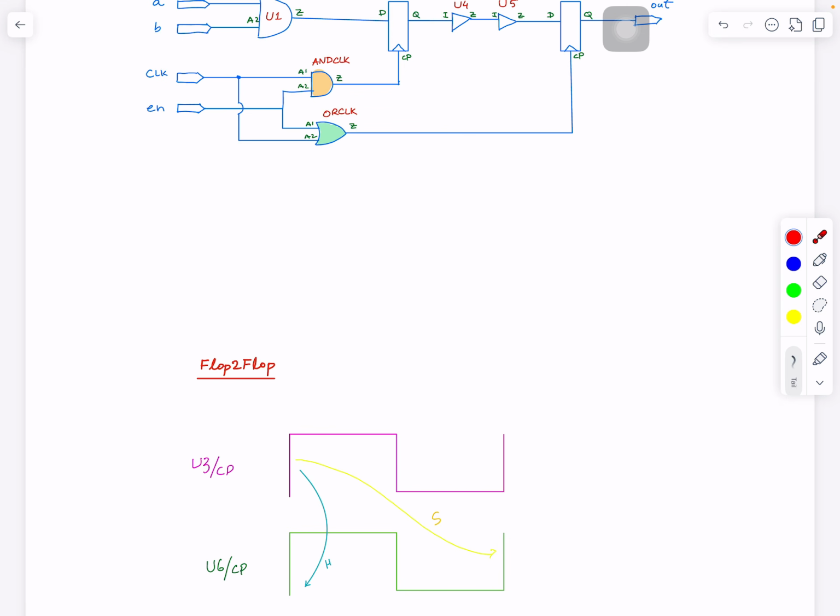Whenever I check setup timing, it is from this side to this side, but there is a setup time which comes from the capture flip-flop, and it comes from the standard cell library, right? So that is the setup edge, rise to next cycle rise. Okay, for the flop to flop, what is the hold one? Hold is launch is the same, and capture is where? And of course, you always remember that there's a hold time coming from the flip-flop, but the data needs to be stable for a certain time here after the rise edge of the clock.